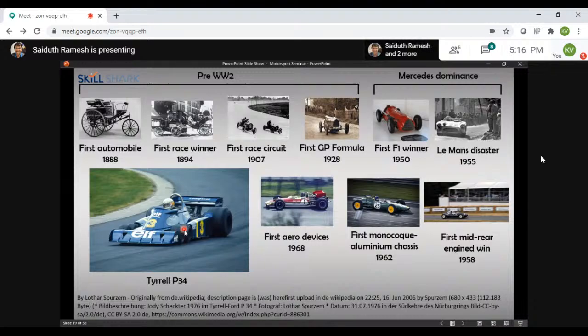The problem with this is it doesn't provide anywhere near enough friction to actually keep the car stable through a corner. As a result, they made it extremely small and fitted another one behind it. This car was very stable, of course, but the downside to having more wheels is you have more compliance, more movements in the car, and not to mention you also have an extra 2 wheels to carry. So it's more weight for the vehicle. Because of this, these cars weren't that popular and they kind of died out over time.